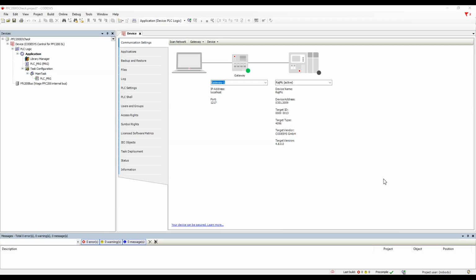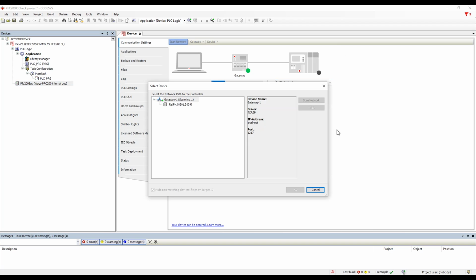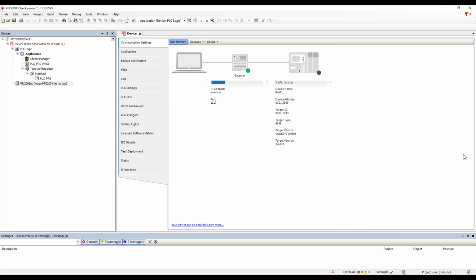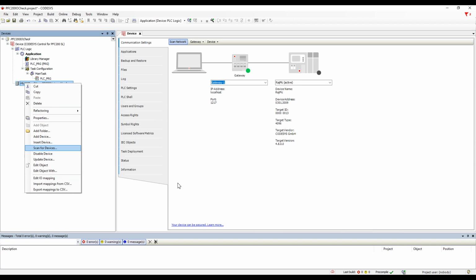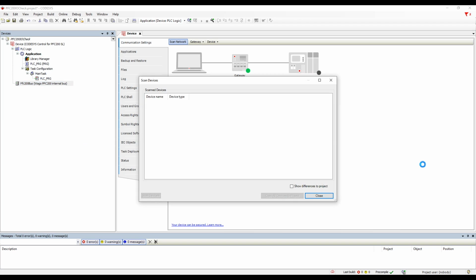So let me talk here about how exactly we will be able to map all those variables in multiple ways into CodeSys. So first thing is to scan the PLC where we have already connected the IO cards. There are two ways, either scan the devices or add them directly into your program and load it. Here I'm going to give you an example for scanning for the devices.